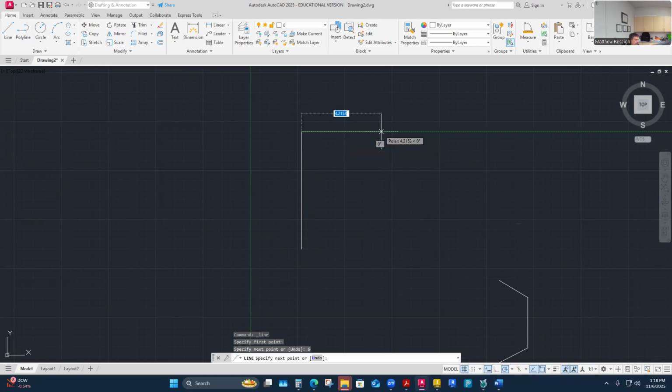I'm usually drawing things accurately. Most of the geometry that I draw, and that we will draw, has a length associated with it that I'm typing in. So it's not just some random thing that I try to figure out later. I usually draw it with the actual lengths that I need, and I'm usually working from a drawing or something that I'm referencing. Next time I'll print out a drawing for you to work from. So if I needed to go 4 over, I'd go 4 over. If I need to go vertical down, I could draw that 3. So anyway, just drawing with those keyboard inputs. Enter means escape the command.